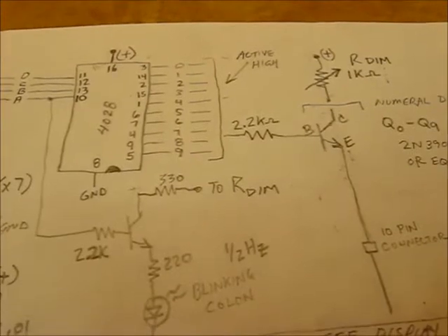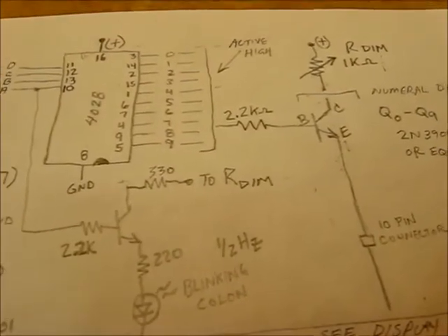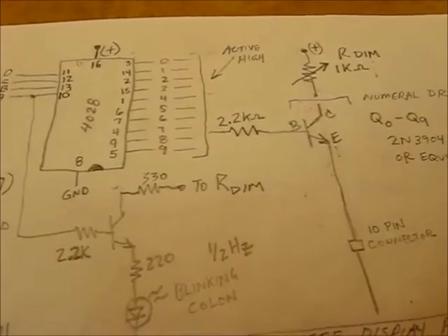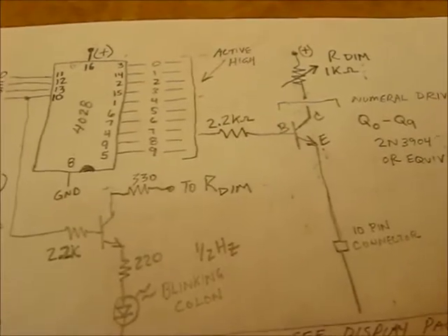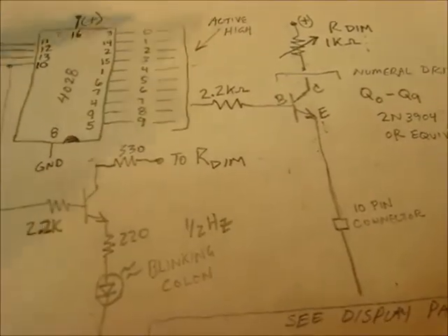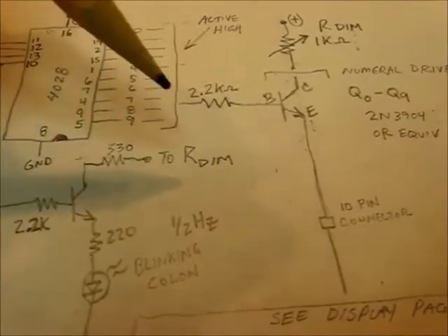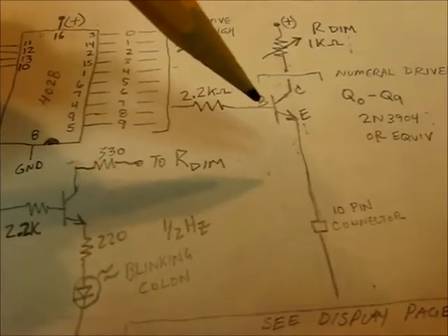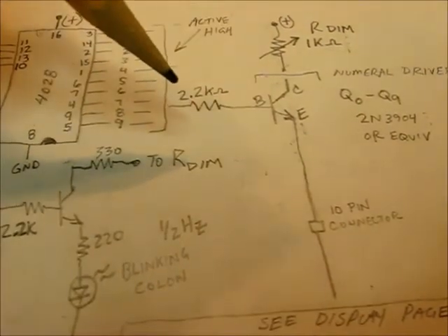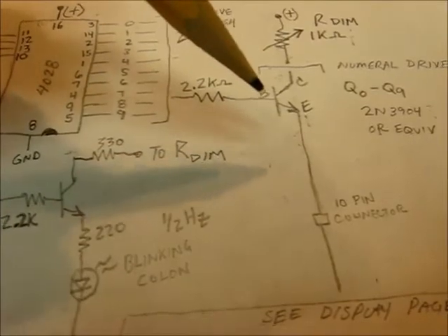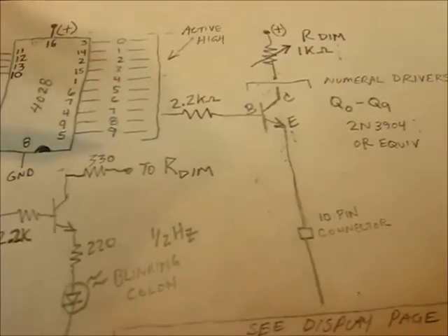And then I had problems with getting the LEDs to work properly. I did not have a base resistor on the 10 transistors. I added a 2.2 k ohm in there, and that made all the difference in the world.